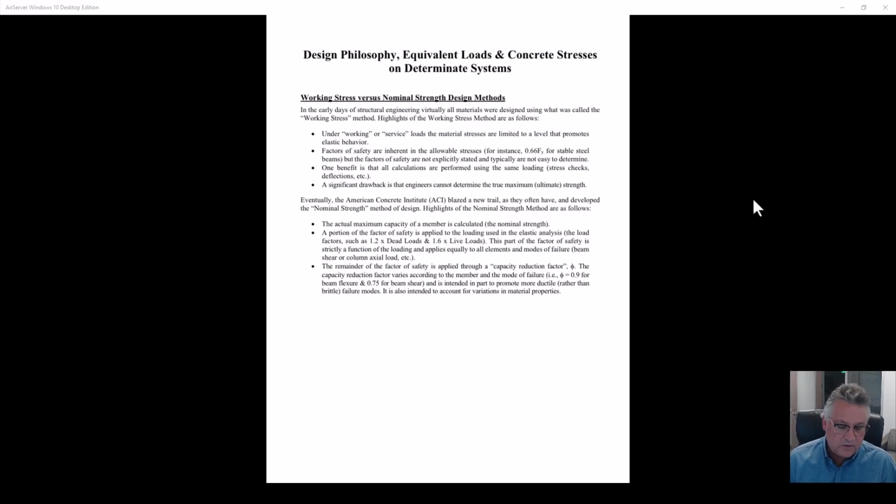In the first half of this class, we are going to focus on the allowable stress part of the design. The code requires us to limit the stresses in the material to basically below cracking. You're allowed to exceed that in some cases, but for our course, we're going to stay at the 7.5 square root of f'c. When you go out to practice, you'll learn that you can exceed that as long as you do certain things. But we're going to stay academic in this. And we'll just keep the concrete theoretically from cracking in our class.